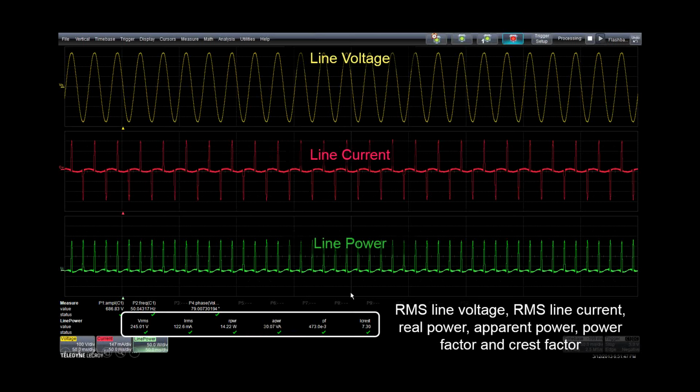So ultimately we get a lot of the power reflected back and not actually used by the device. The difference between the real power and the apparent power is that the real power can actually be used to do work by the system. The apparent power is just the voltage times the current, and the difference of that is what actually gets just reflected back to the source.